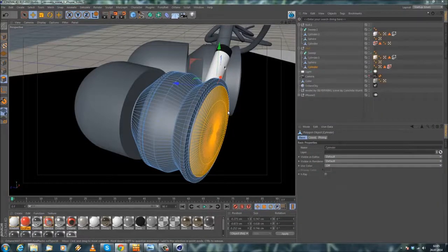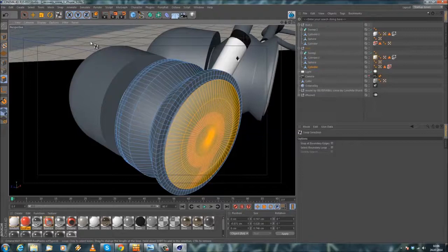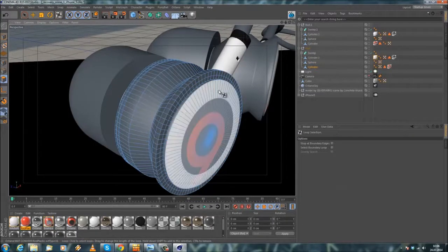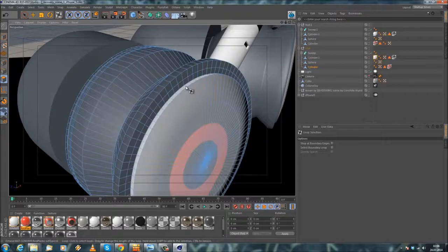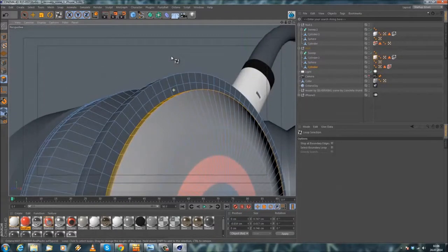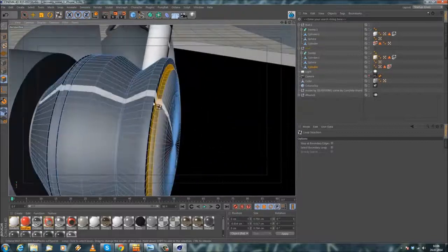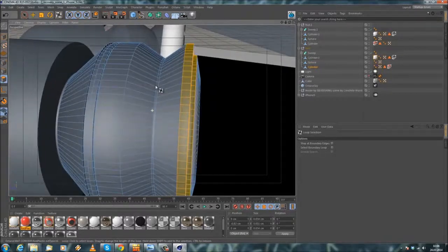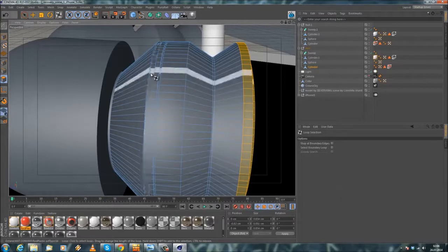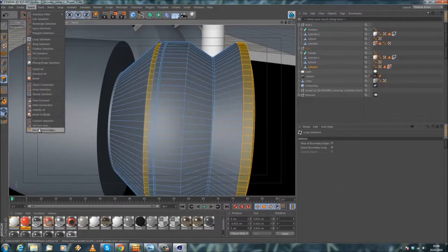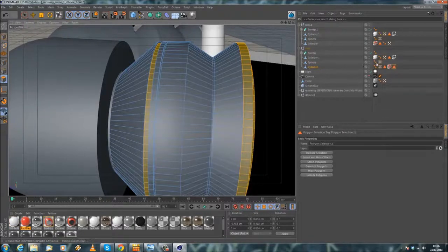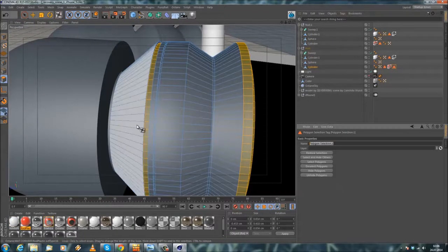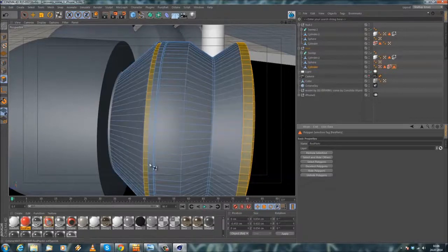Okay, here in the back, first of all, select loop selection. Make sure that you click anywhere in the scene so you get rid of this selection. Then we select this here and also this here. Then we should have a small ring right here that is red. Yeah, this one. Okay. Then here is nothing, and this one should be red. Okay, so select set selection. Yes, and we call this red parts. And hopefully this works for the other cylinder as well when I copy this over.